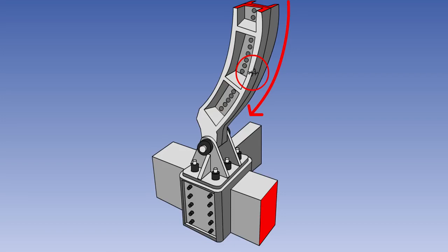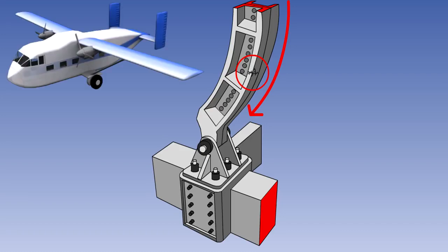The disadvantage of duplicating the load paths is that it is very expensive in terms of weight, as each of the members has to be strong enough to do the work for both. It is now only normally used for wing and stabilizer attachment points. The bracing struts between the wings and the fuselage of the Short Skyvan, for instance, are each made up of 3 members.